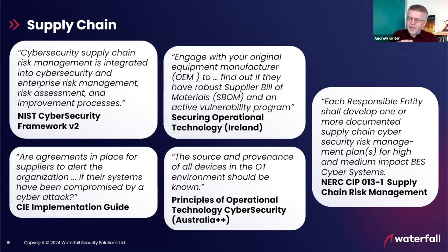And can we account for everyone who's touched those things between the organization that allegedly produced them and us as consumers? Was there a break in the chain where a counterfeit device might have been inserted? This is a big problem in safety systems, safety instrumented systems. You absolutely need this kind of provenance to figure out, am I buying an authentic, expensive, extremely reliable safety instrumented system? Or am I buying a cheap, unreliable system that has all the same labels as the expensive system, but in fact, someone is deceiving me and they're not an authorized seller of this in my geography?